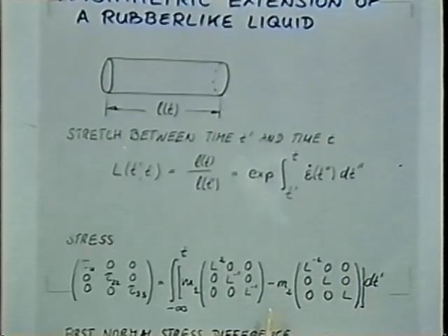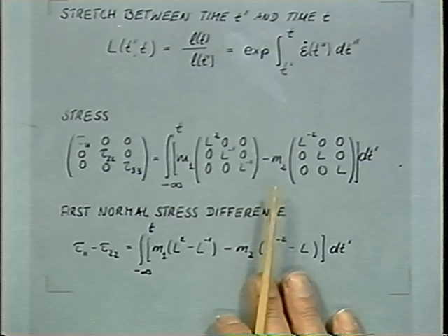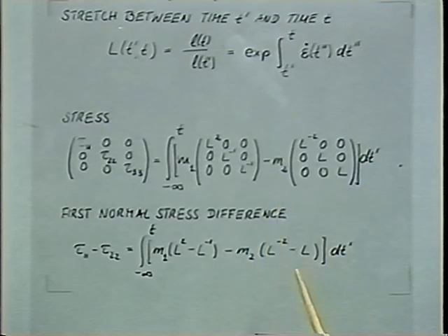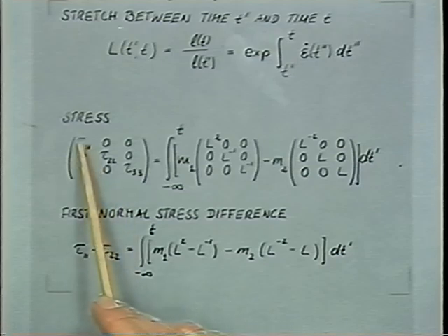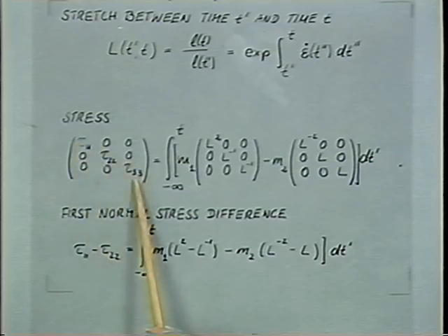The resulting stress, which we calculate now using the most general equation for viscoelastic material, staying, I would say, most general if you stay with a single integral and if you stay with linear viscoelastic properties. So the stress is given by the diagonal terms. We're choosing a principal coordinate system.